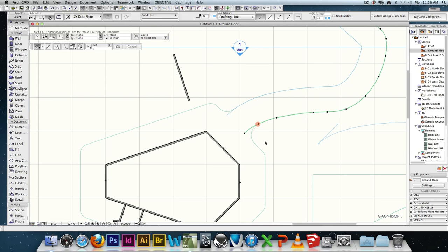Beautiful. Okay? And I could eventually turn those lines off, put them onto a construction drawing layer or something. They're always handy to have, because I have to recreate this. I've got them. Same thing with that spline. I should have really had it on another layer and just switched that layer off. So I can turn on my construction splines, and I've got all these nice curves that I used to create it in the first place. So if the client comes back and says, I love that path, but I don't like that corner up there, can you smooth it out a bit? I could go back to that original spline, adjust it so it's a much nicer curve, create my nice, beautiful curving paths that follow it and recreate the 1500mm offset.